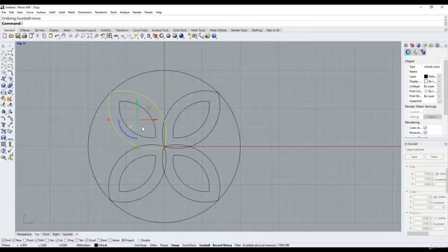So I want to perhaps, I don't know, maybe make that a little bit longer, push it to the outside of that 20 millimeter circle. I want to scale that out, if you will. So let's type scale. And you can see we've got some options here. Scale, scale 1D and scale 2D. I just want to scale it in one direction. So I'm going to scale, hit that button from this point here to that point there.